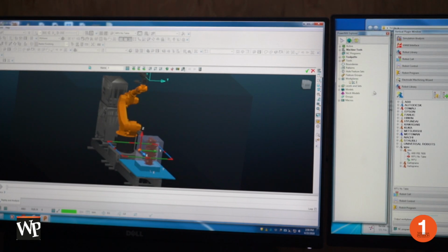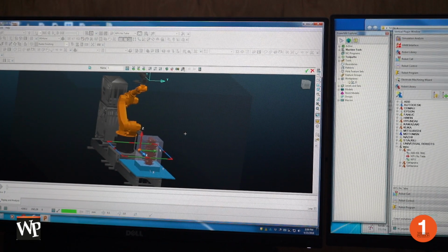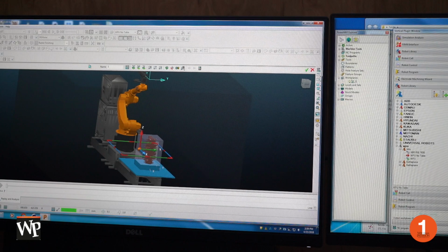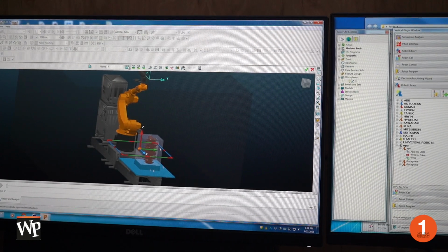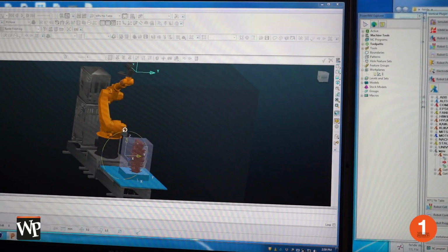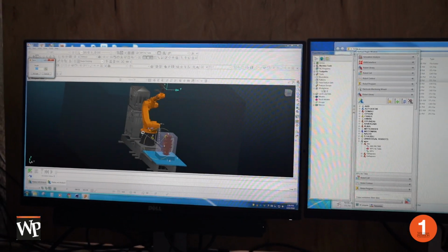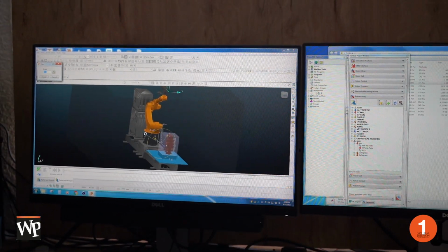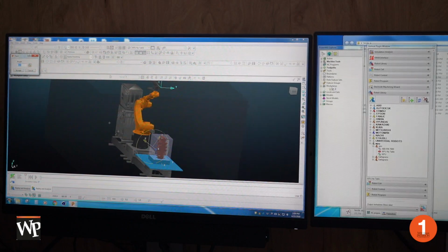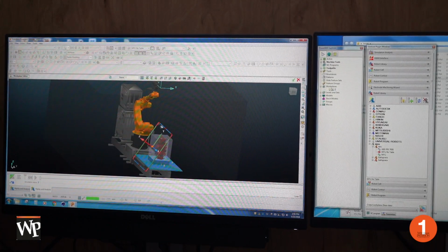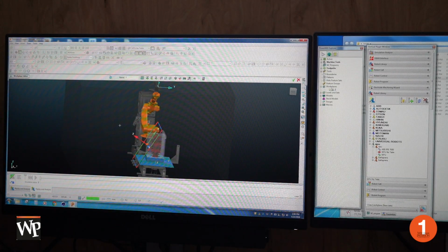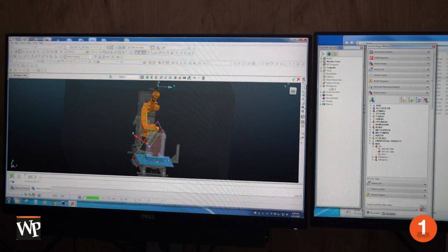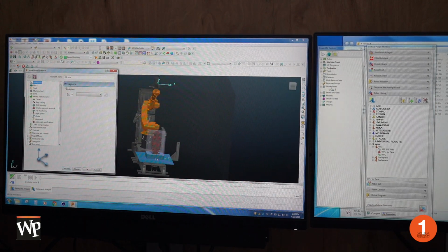We've found that a 60 degree angle is a good angle to work at. So we're going to twist this work plane on the X so that it is 60 degrees. I'm going to accept that. So now this is the angle which our tool is going to come towards our model. I'm going to click the green check.